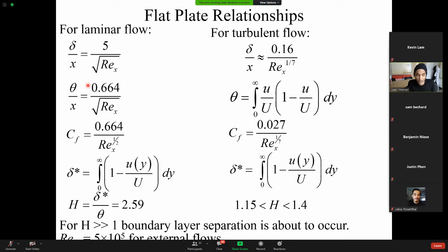Yeah, so by definition, we use this critical Reynolds number value of 500,000. In reality, it's actually very difficult to know where it happens, because it could be 510,000, it could be 499,000, it could be 495,000. But for an exam, it will be 500,000. In reality, if you can make a plate really, really smooth, then you can delay it. But for an exam or course, just use that 500,000 value. That's when you'll get that critical Reynolds number.